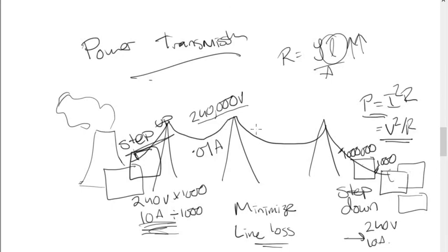So current যদি কমায় দাও, then the energy loss will be less, the PD across the wire will also be less. So that means what? V square by R যদি তুমি পরেও calculate করো, তখন তুমি দেখবা যে voltage change টা across the wire is actually very small. এত পর্যন্ত clear?